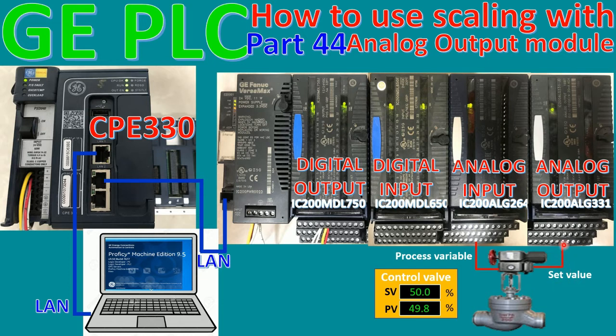Here is the analog output module, and I will send the 4 to 20 milliamp to the control valve, and the control valve will feedback 4 to 20 milliamp also to the PLC analog input, and then it will show on the HMI. So we need to create the set point value from the HMI and send the signal to the analog output and then connect to the control valve.